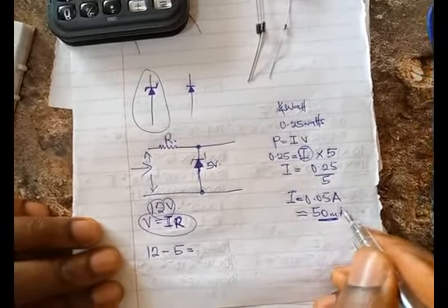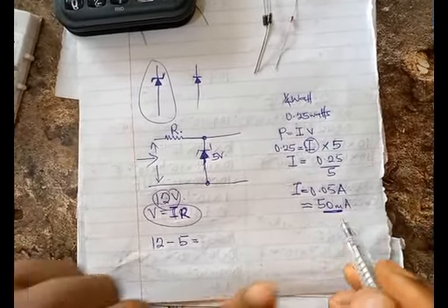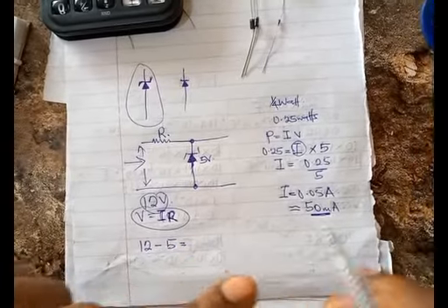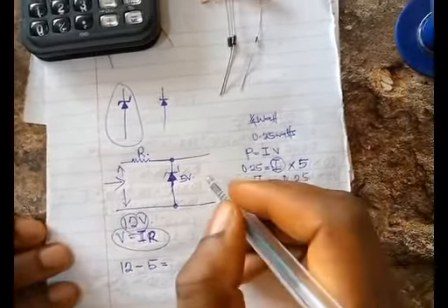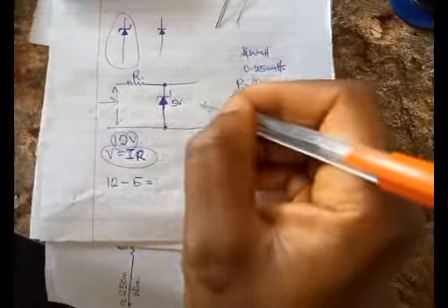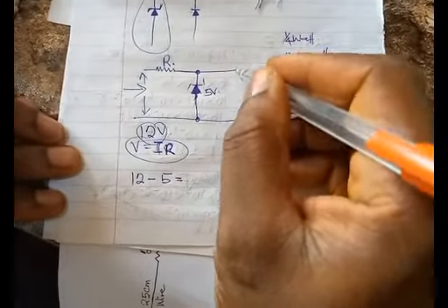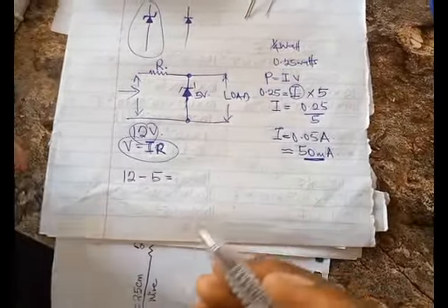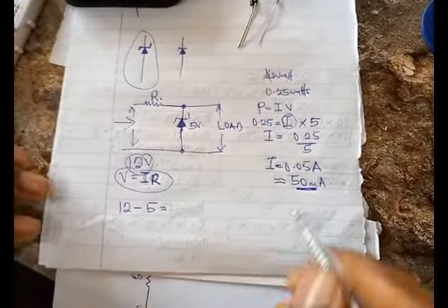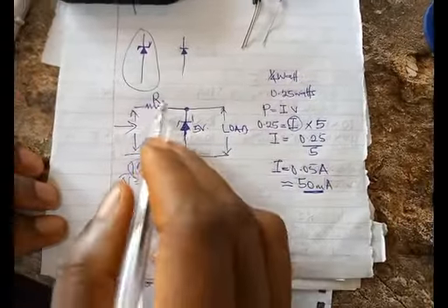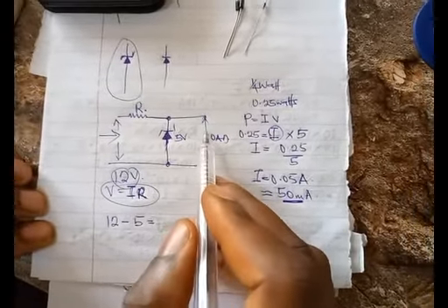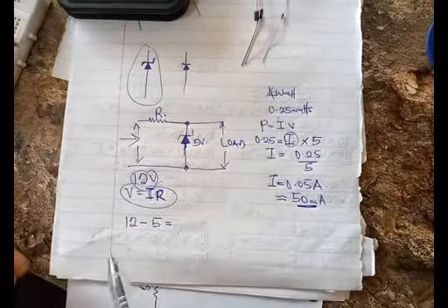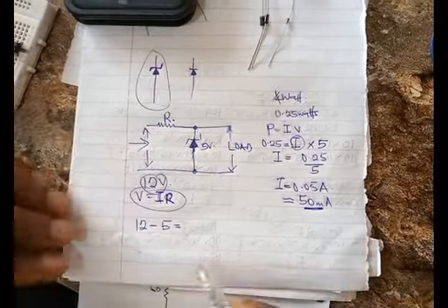We want to limit it to 50 milliamps. But remember, now the Zener diode will be sharing a particular current with the component we'll be putting at the output. Okay, there will be a load here. So we'll take that load into consideration. We're assuming that 50 milliamps is the maximum that this guy can take. But remember, when it is loaded, the Zener diode and the load will share whatever current we are putting into consideration.